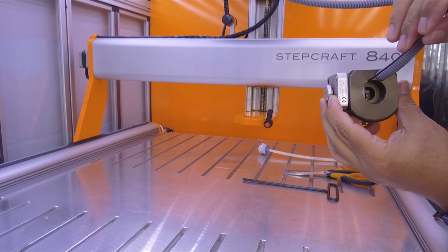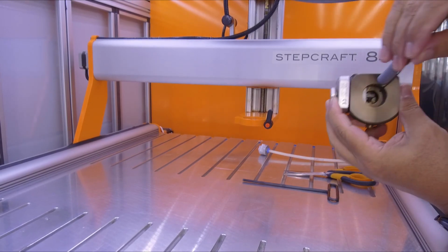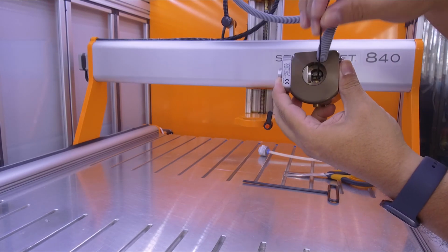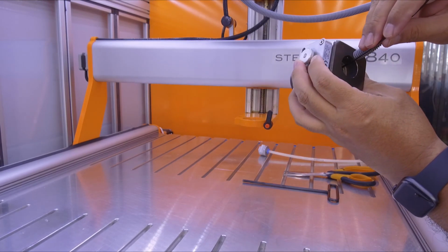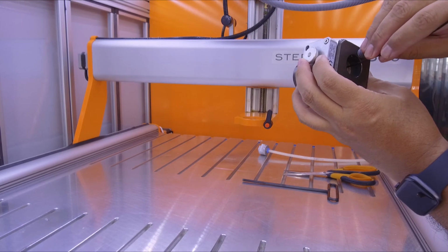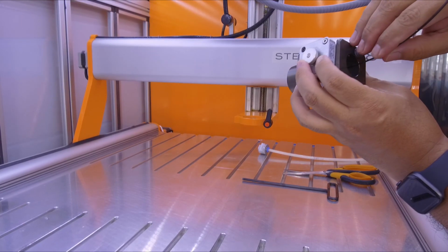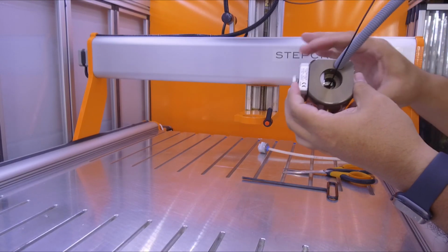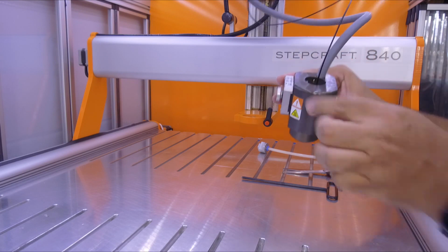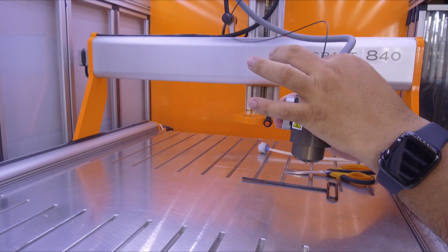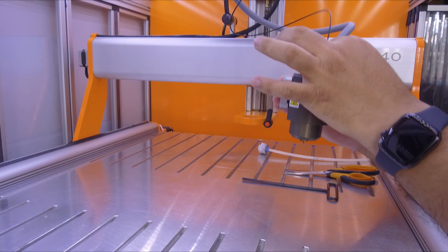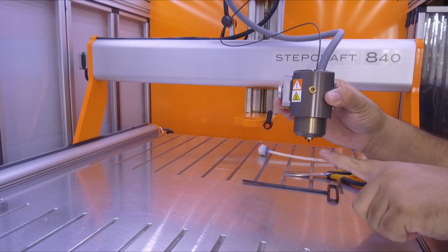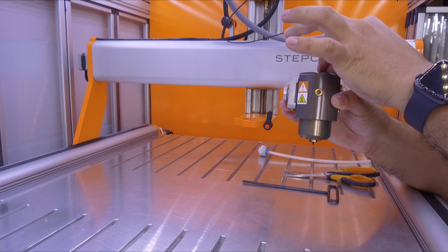I'm going to put the filament, I'm doing this so you can see it. I'm going to put the filament inside here, between the pulley and the gear. So right now I can see that it's inside the hole, and if you see, this is loose. So if I press this a little bit, you can see that the filament starts flowing from below.